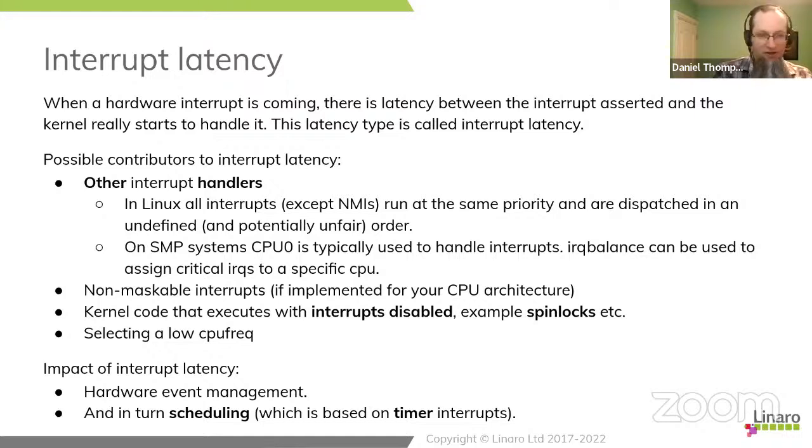Undefined is a principle. All the drivers are written on the assumption that the order in which the interrupts will be dispatched, if they're competing, is undefined. In reality, it's closer to architecture defined. So on an ARM system, when you've got multiple interrupts firing into a GIC and all those interrupts are the same priority, the GIC will pick the one which has the smallest number. Not SGI, sorry, I beg your pardon, SPI, shared peripheral interrupt. So the one that has the lowest number is the one the GIC will select.